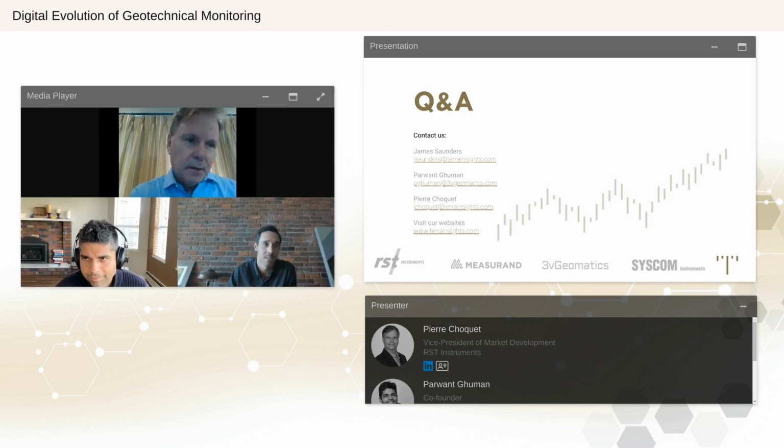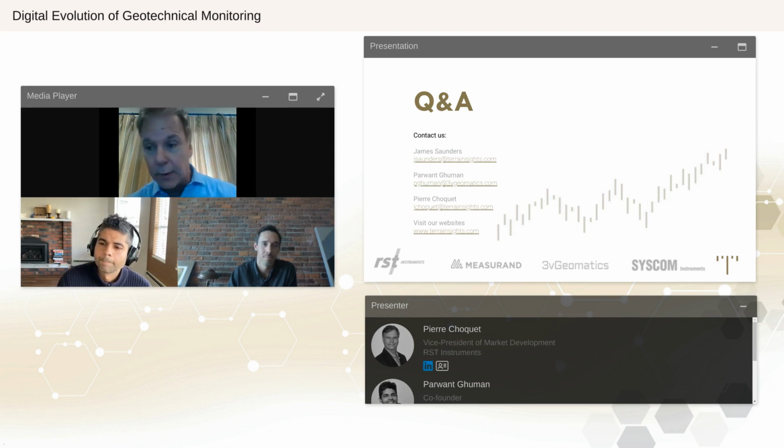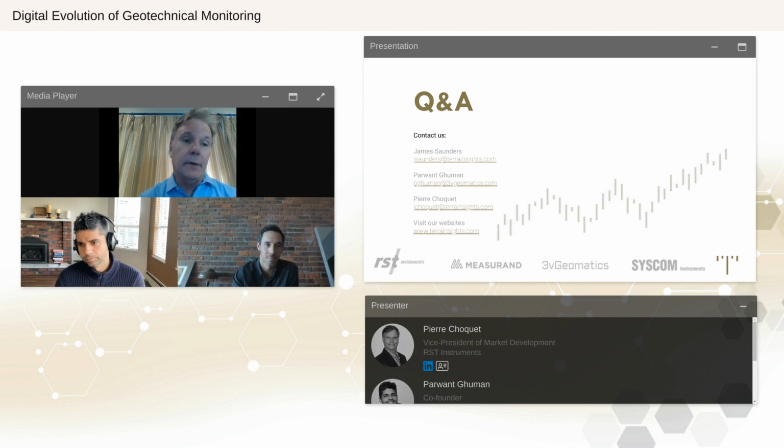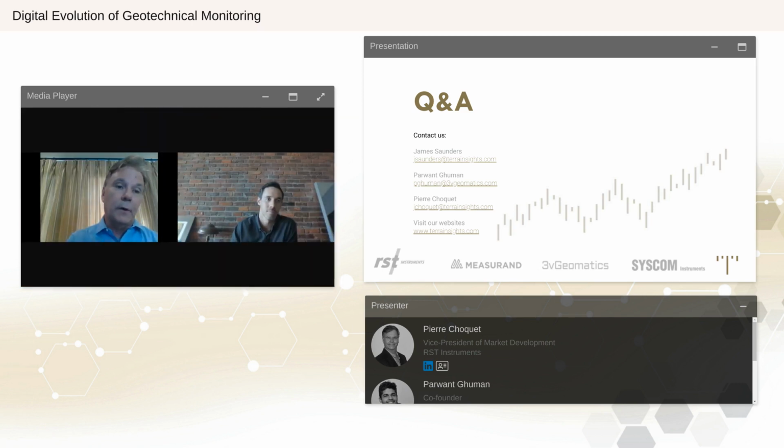Go ahead, Pierre. I was going to say very briefly, there is the option, of course, of monitoring certain main critical sensors at a reading interval that could be almost close to a second. Actually, that's feasible if it's really one that is related to a failure mode on which you would like to have alarms. A good consideration is not all sensors need to be monitored with the same interval. Yeah, I'd agree. That's great.